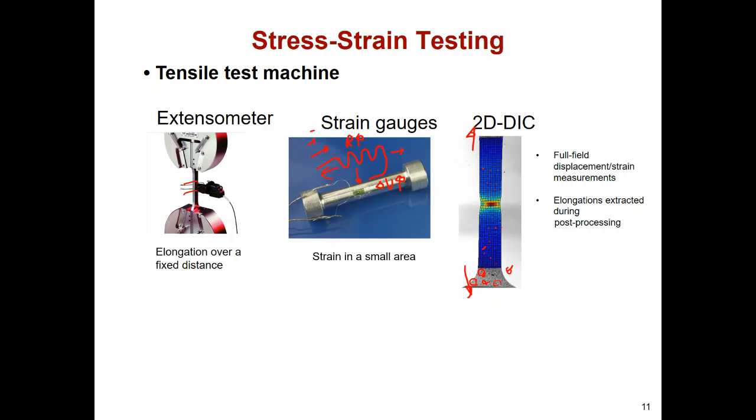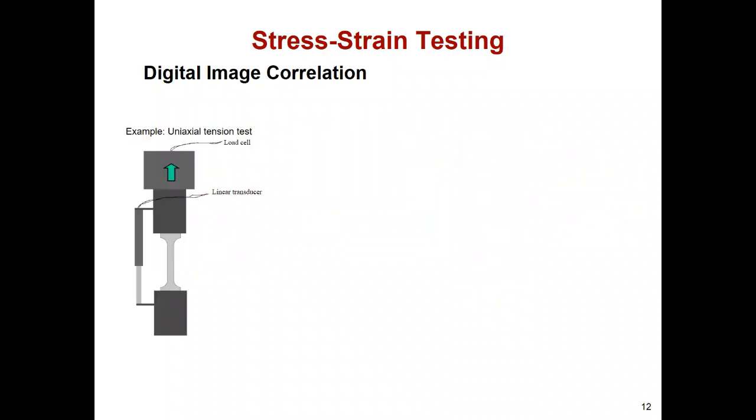The advantage of the digital image correlation method is that we do not need attachments like strain gauges, extensometers or mirrors. The disadvantage is that without some geometric graphical mark, it cannot determine the exact deformations. But these days, digital image correlation, a non-attachable measurement technique, is well known.